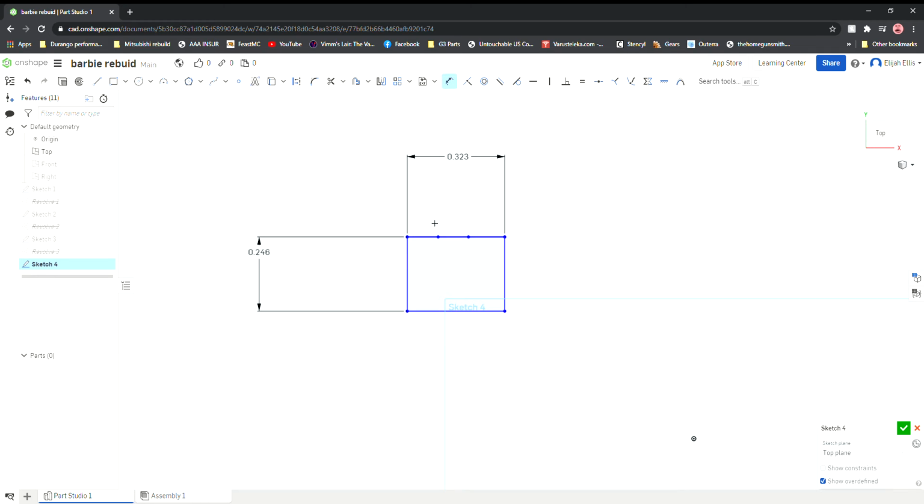Anyhow, since we already have our constraints here, it must be this tall, this high. Ooh, I almost forgot. Since I'm going to be making this a revolve function, I'm going to have to pull up my calculator here. 0.246 divided by 2, that's 0.123. There we go. Now we got half of it. Now we're going to be dividing this up into our little squares here.